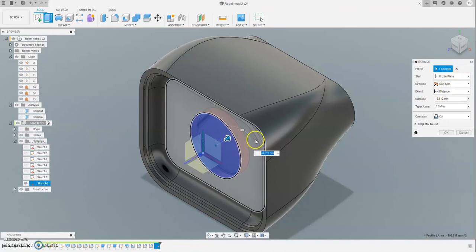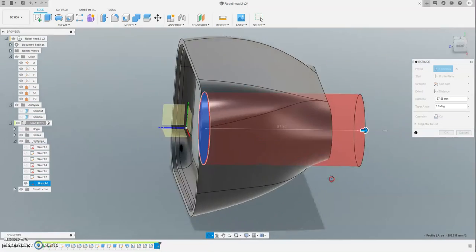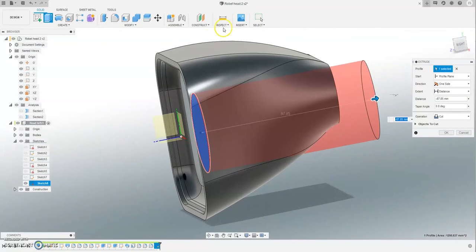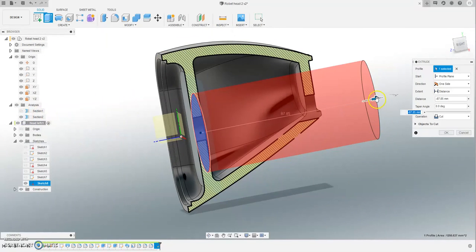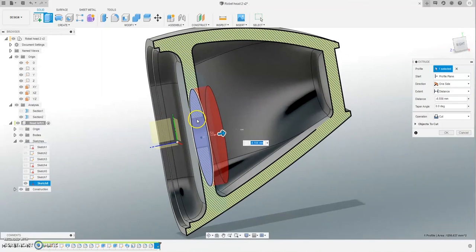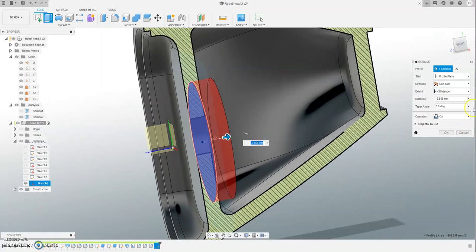and do that to the next surface. Now, I'm doing that because I don't want to drag that back. If I drag that back, I run the risk of it cutting through the back. Let's have a little look what that looks like inside. So I'm going to switch on my section there. So I could drag that back in. Now I know that the thickness of that wall is 6. Never do all, it'll go all the way through.